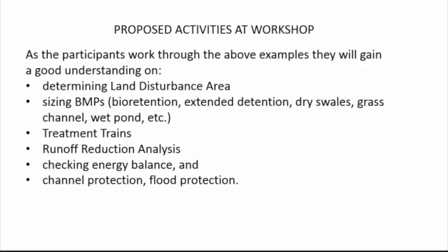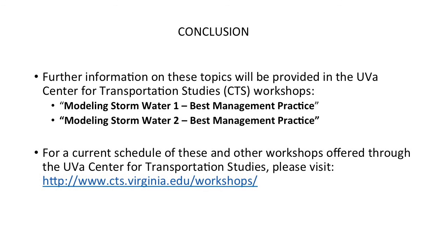As the participants work through the above examples, they will gain a good understanding on determining land disturbance areas, sizing of BMPs, bioretention, extended detention, dry swales, grass channels, wet ponds, etc. How to deal with treatment drains, runoff reduction analysis, checking energy balance, and channel protection and flood protection.